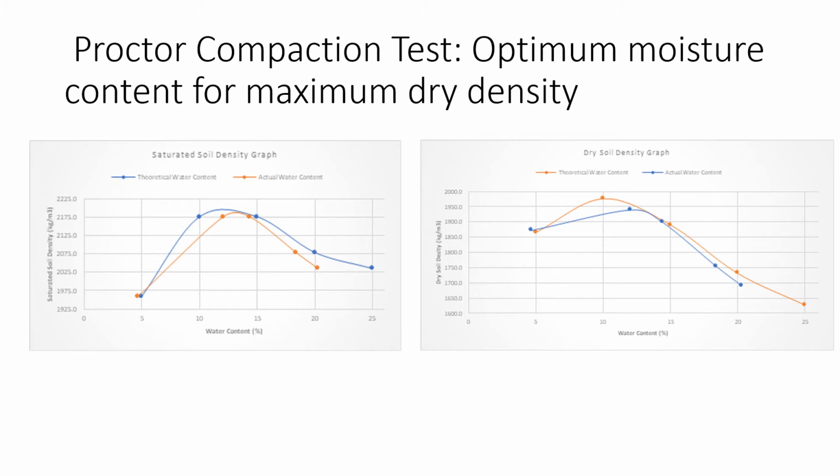Meaning that the structure of the soil will start to deteriorate above 12% water. However, our results show that the soil can keep its structural integrity in the water content up to 15%. This is more than enough to support the building loads, as it is highly unlikely we will reach such a high content.